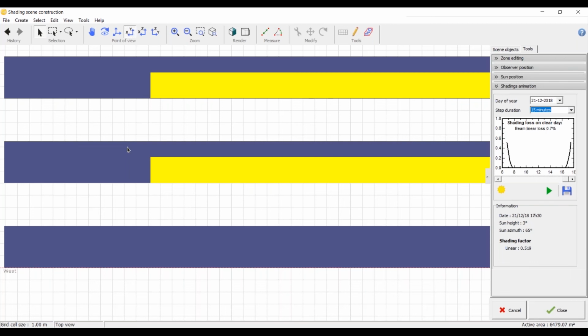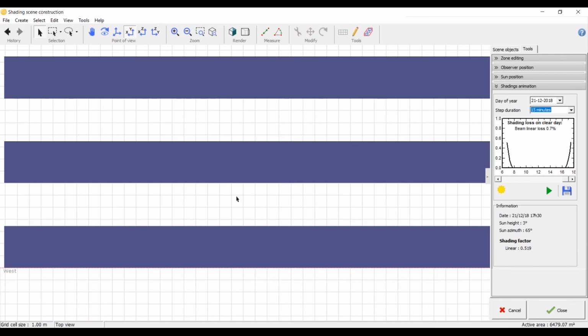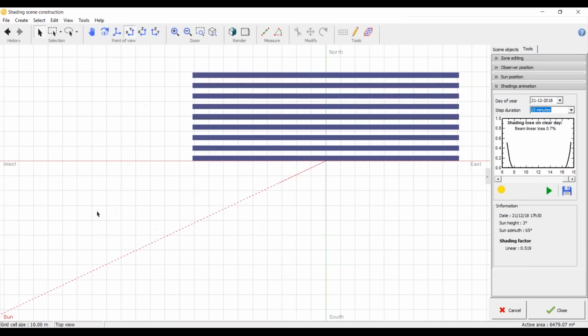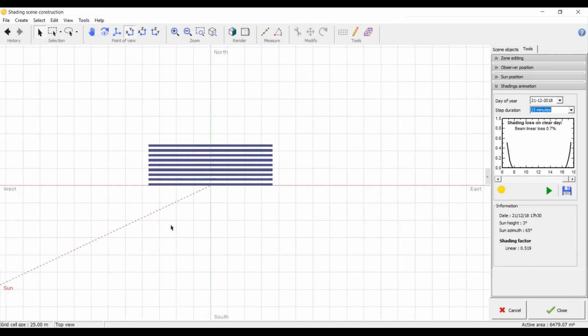If you have a microinverter, that's a different story. But with a system where you have a whole string of 18 modules, then you don't really produce that much energy. But when you don't partition the whole array into strings, what PVsyst thinks is, okay, only 50% of the overall area of the module is shaded, so the remaining 50% is actually producing energy. But in reality, we wouldn't be seeing that much energy from the PV. So it's always good to have a partition once you're done with the initial array. So we do this, and then I have another thing that I would like to show you.